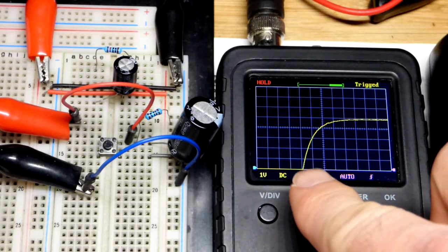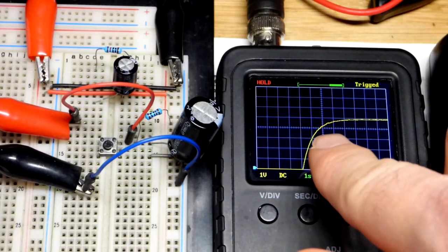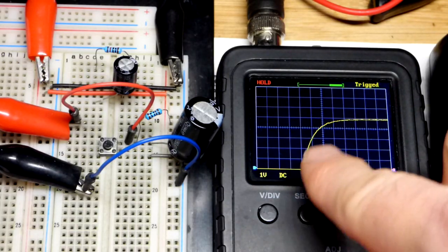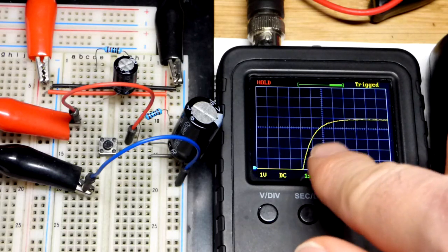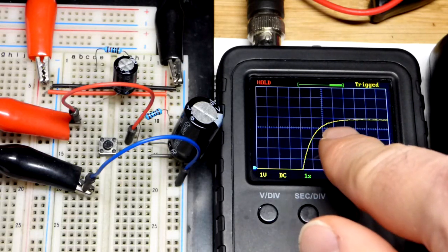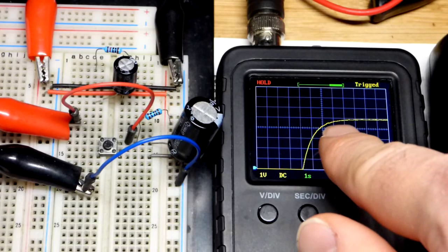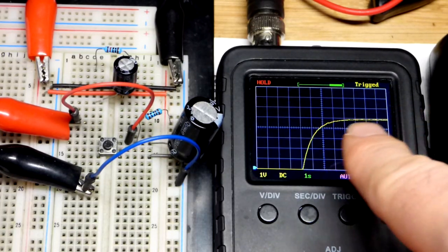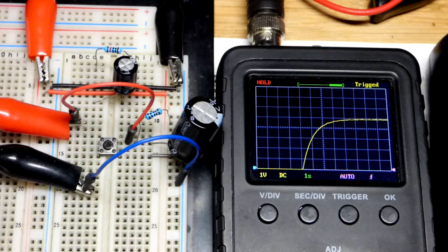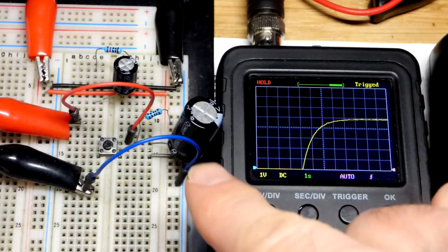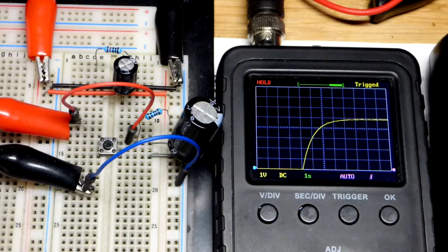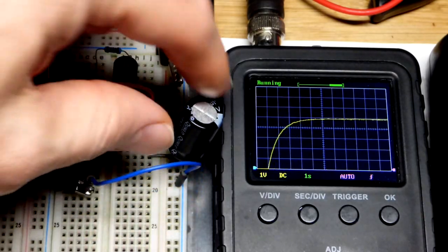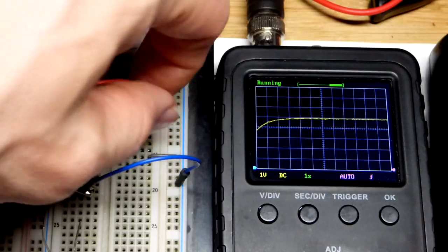First second, you got about 2/3 of the total difference. You can see we're up to about 3 volts right there in the first second. And then the curve curves, and we're only about a volt and a little bit more, and then not even a volt, and so on. And after about 5 times, you consider it about leveled off. It's going to trickle charge a little bit. But in any case, that's how you look at the time constant for capacitors like this, based on the resistance and their capacitance. We're going to look at that in more detail.